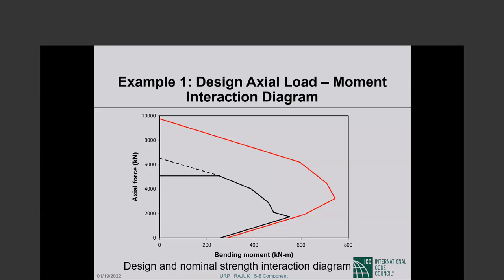Well, it is sometimes required, not all the time, but in seismic situations, which is much of Dhaka, you have a column supporting a discontinued shear wall. The column cage has to continue at least 12 inches into the support. So there are cases where you are required to continue the column ties into the foundation.